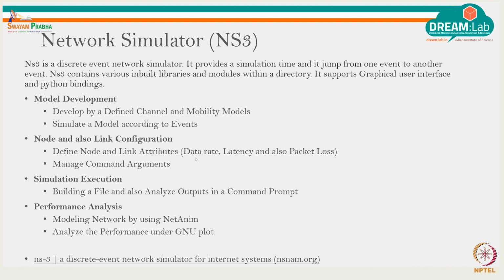The other thing is when you want to know the link performance parameters of your setup, whether it is data rate, latency, packet loss, or throughput; a lot of things can be examined using NS3. It's not just the UI that is available with NS3, but in case you want to specify the kind of protocol you are using, the session you are using, or the number of nodes that you have, you can use the command prompt to simulate your environment.